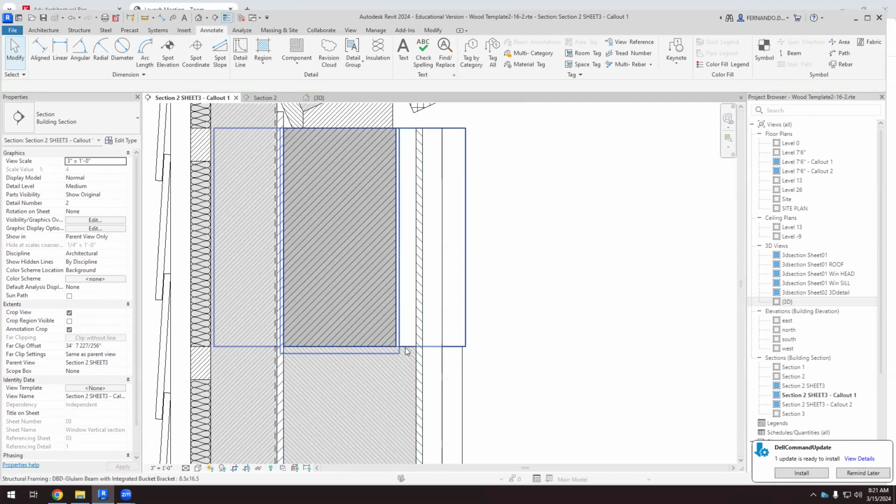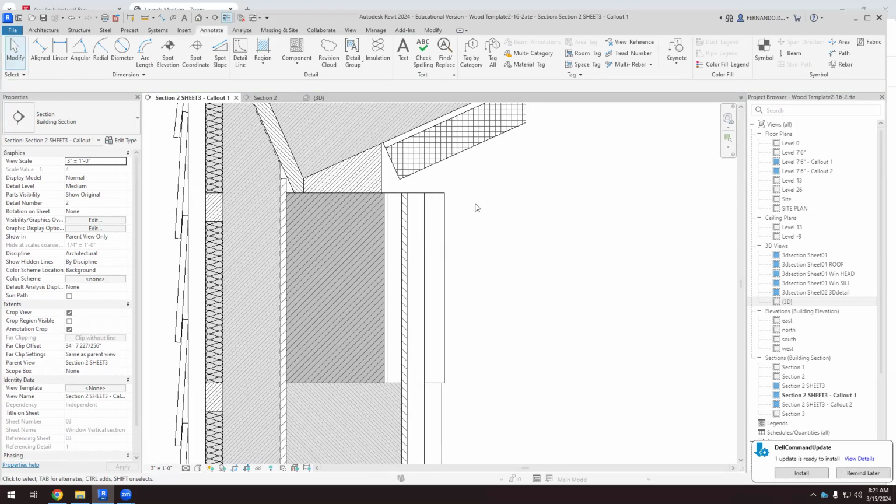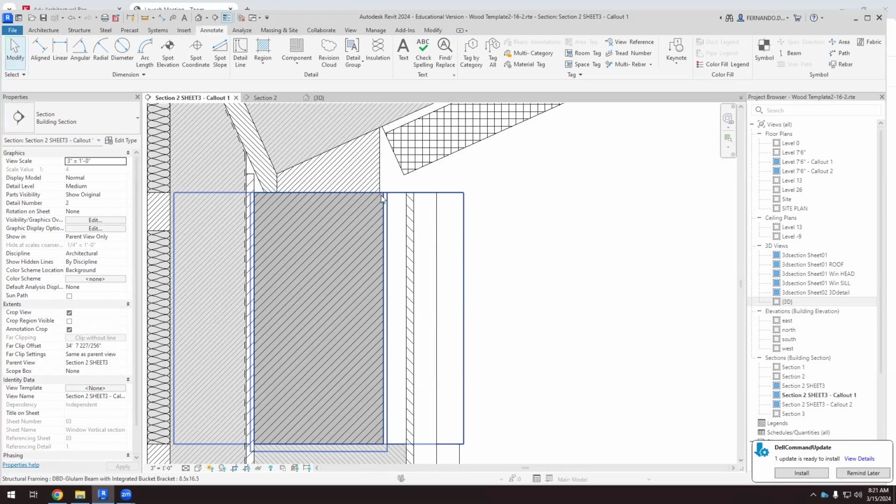We have the opportunity here because you see that the structure is thinner than the thermal insulation cellulose that we have here. Okay, so before moving this up, I think we can fill this gap. And sometimes when we have a gap that doesn't have a regular shape, what do we use? We use foam.